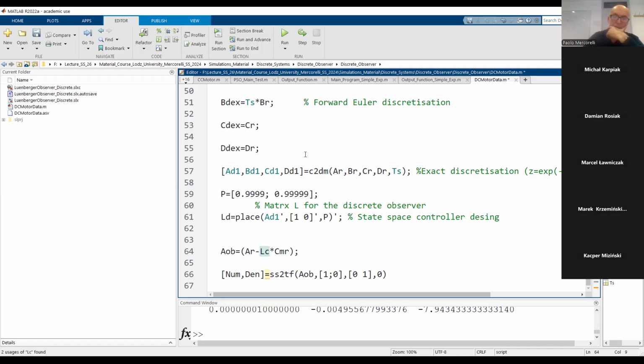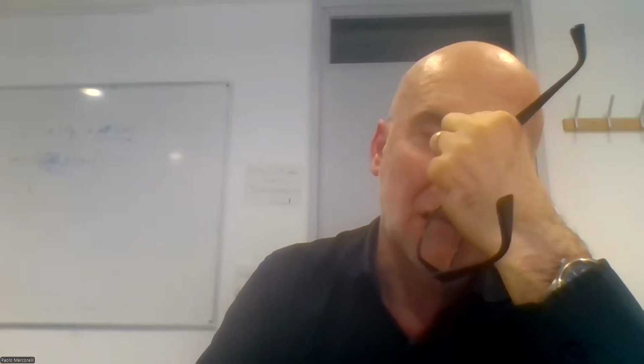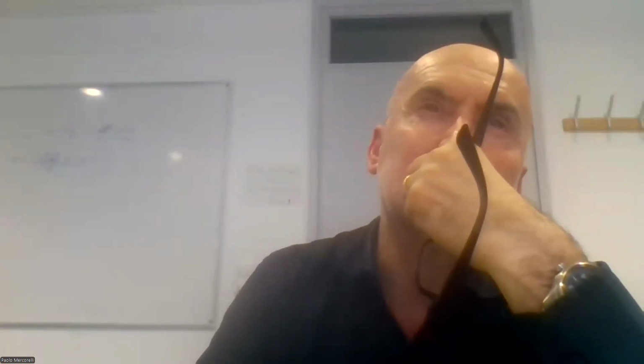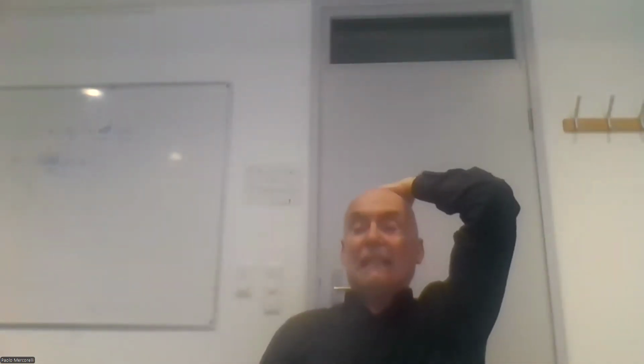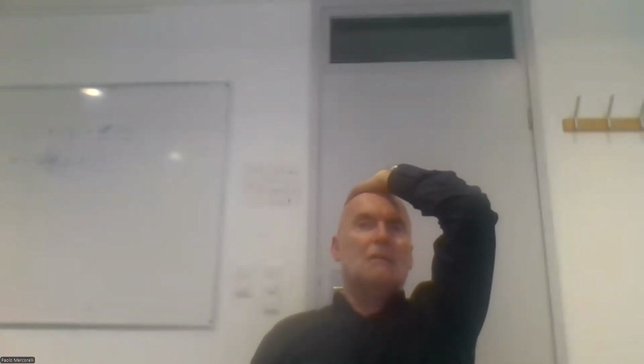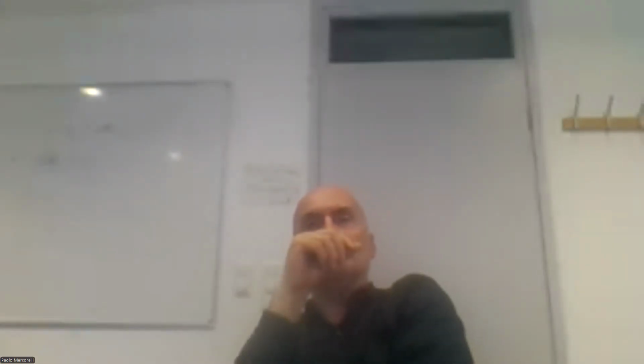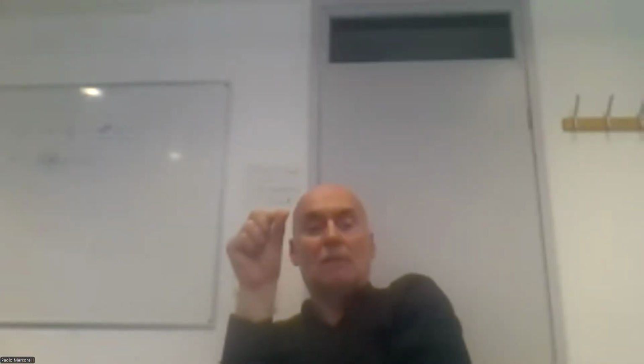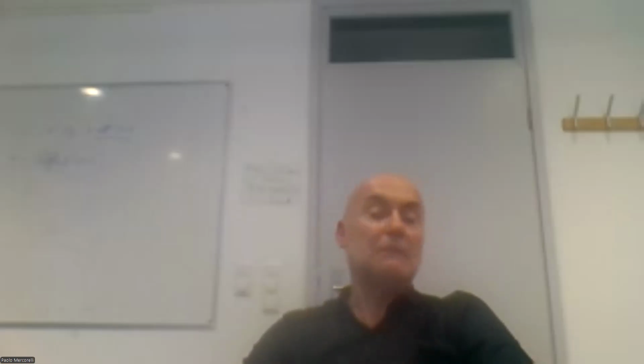Okay, I will think about how we can show you this non-minimum phase effect. And I will tell you in a particular form and in a particular analysis next week. Let me see if I find a better way to show you this non-minimum phase, where we can see that the numerator of the transfer function related to the observer consists of a positive zero. Anyway, let me look at MATLAB.